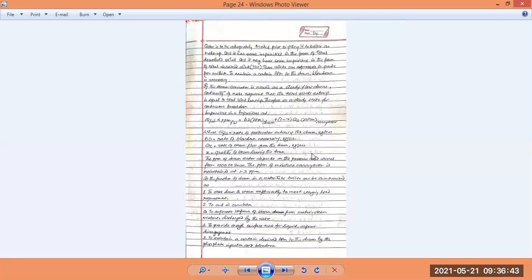You have to raise your supply or lower your supply as desired. All these things are supposed to be done by the supply of high superheated steam, and you see that the drum plays an important part in storing it and supplying it according to need. Then the drum should have sufficient water in circulation, because due to natural circulation, the intermediate function of the drum is carried out very easily.